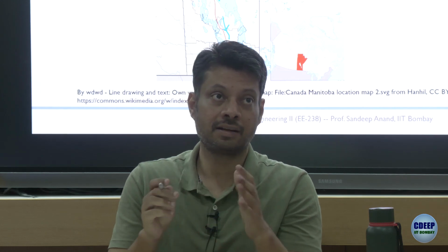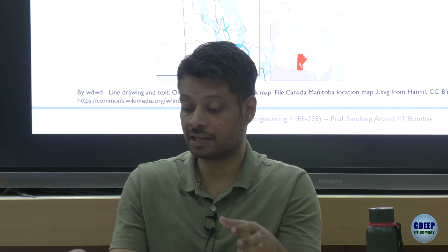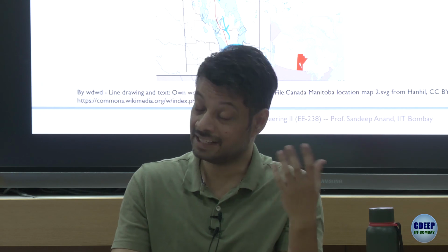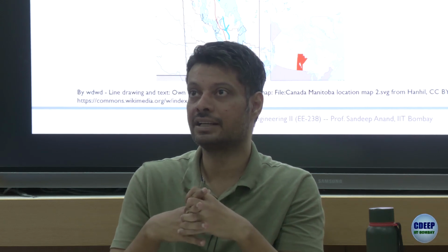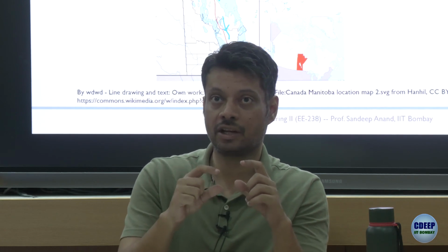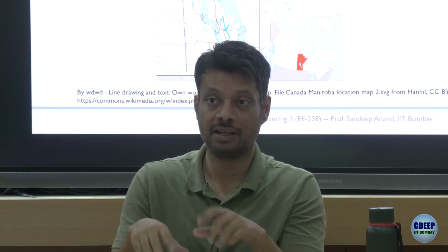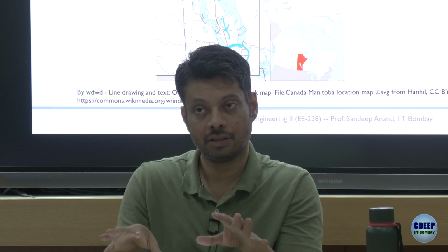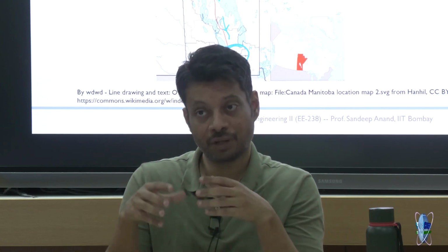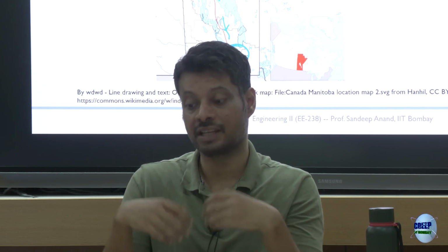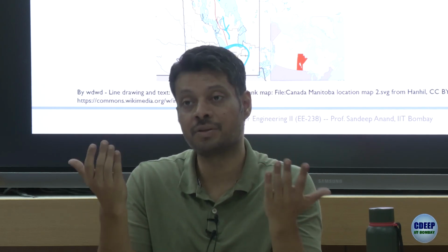So look, there are quite a few practical reasons why that doesn't happen. It didn't happen at that time, and even today that doesn't happen so much. At that time, why it didn't happen, you can clearly see, right? You don't have that kind of boost converters. A boost converter cannot operate with the same switch, by the way. It requires a fully controlled switch. At that time, you didn't have a fully controlled switch. Even today, you don't have a fully controlled switch which can handle 150,000 volts.